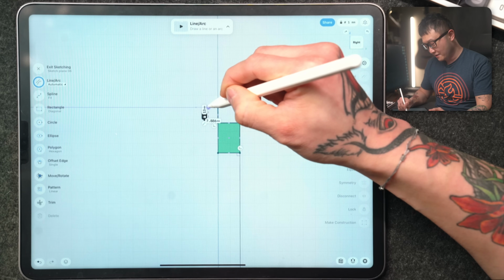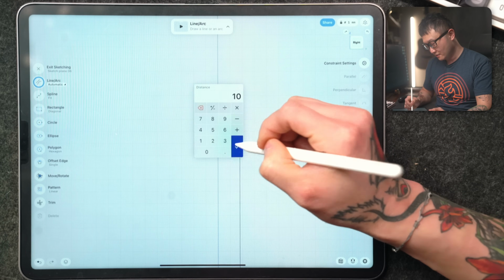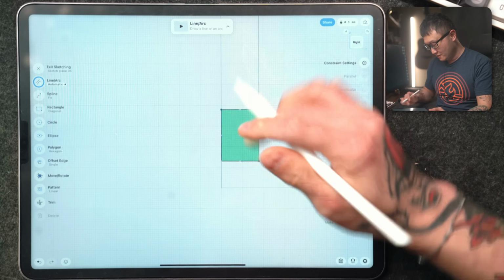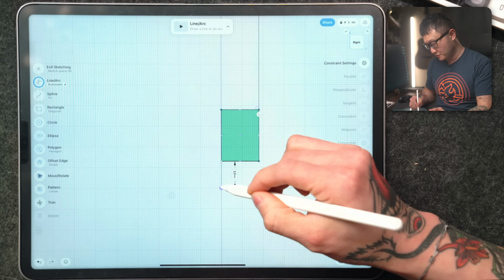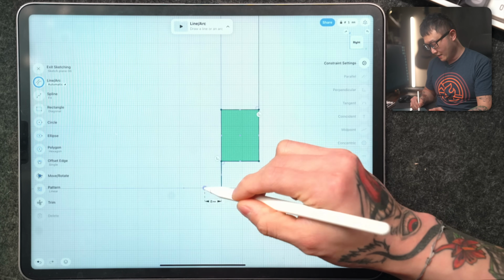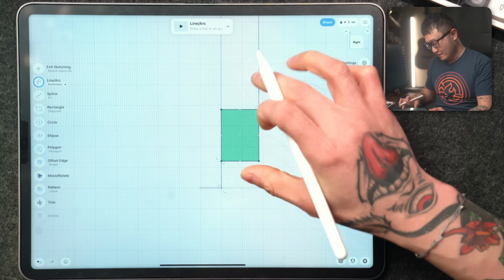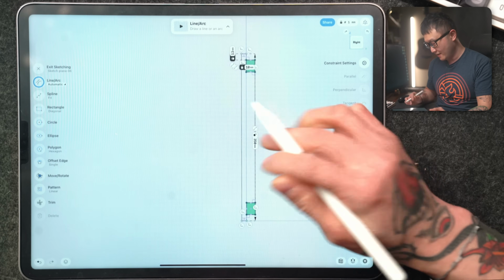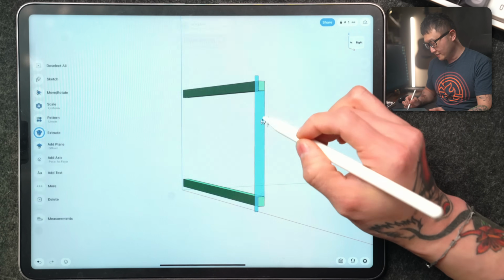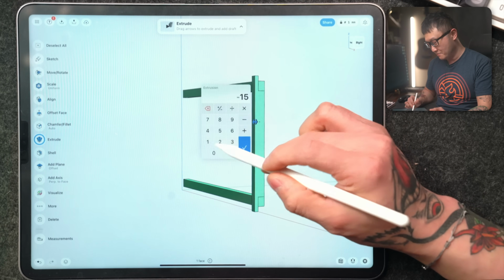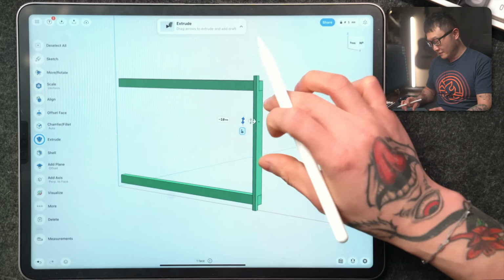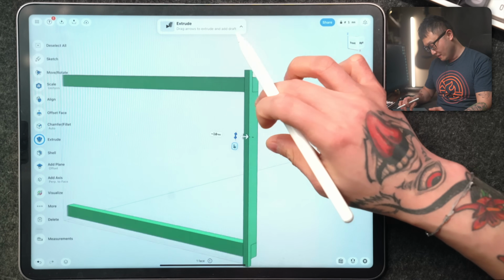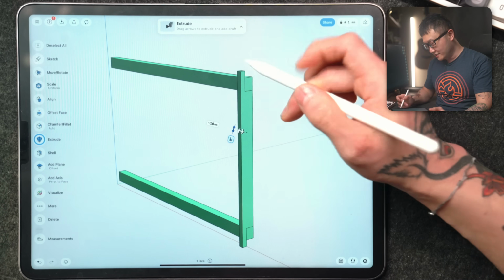And then we'll go left 10 millimeters. Let's do the same thing on the bottom side. So come down 13 millimeters and then left 10. And we're going to finish this sketch by connecting these endpoints like that. Now let's pick this face and we're going to extrude that 10 millimeters. There we go. So that's one of our, well, actually, let's add a chamfer on the ends here.